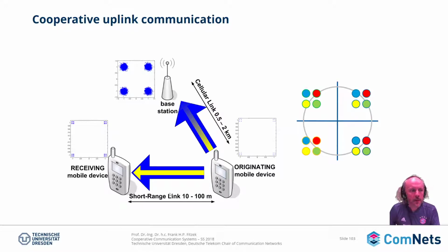What you could do is take, for example, a 16 QAM modulation, and what you see here seems a little bit strangely originated. Instead of placing the points equidistant, you move some of the points to the left upper corner, to the right upper corner, to the left lower corner, and to the right lower corner. So it's called heterogeneous QAM. They sometimes also do this in DVB-T for heterogeneous transmission of some frames they want to protect more than others.